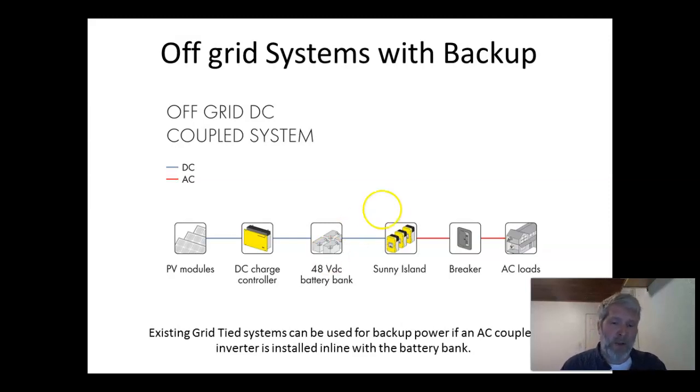Now, you would think that you should just be able to use the same inverter, but the inverter, if it was a string inverter, is actually designed to be able to run at somewhere between 300 and 600 volts, while this is only a 48 volt battery backup system. If you're using lead acid batteries and you have 4 batteries in series with each other, 12 volts apiece, or potentially even 8 batteries in series if they're 6 volts apiece, 6 times 8 would give us 48 also.